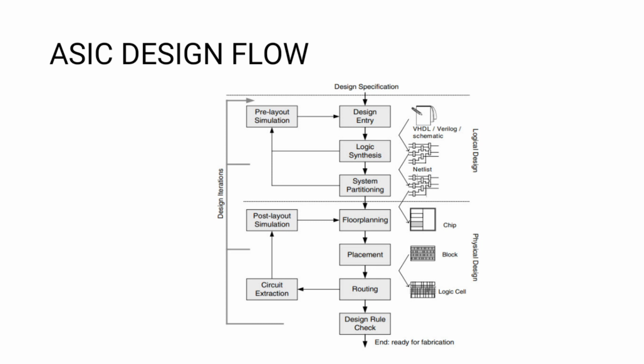After that, logic design. Once the documentation is over, you need to convert that design concept into a program. That is done by the Verilog and VHDL hardware description languages. After that, we go for a simulation. Once our code is ready, we must check whether it will work properly or not. For that, we have a simulation process.